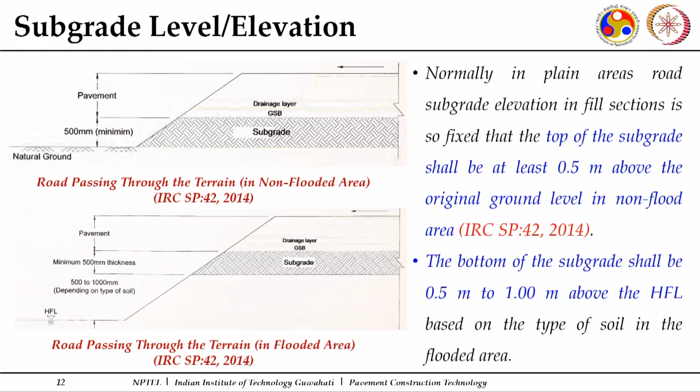Depending upon what type of construction is there and what the guidelines say about the strength of that material, you can use it once it has been approved by the engineer in charge, who will use these Codal specifications to select whether this material is suitable or not suitable. Now as I said, there is always a concern: this forms an important foundation for your pavement structure. So you need to keep the level of this in a proper manner, so that it does not get submerged by water.